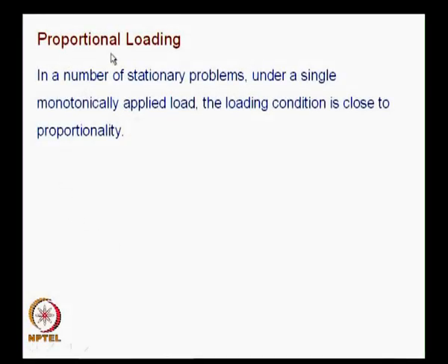And here you have a little more expansion on the terminology proportional loading. In a number of stationary problems, that means the crack is not growing, under a single monotonically applied load, the loading condition is close to proportionality.